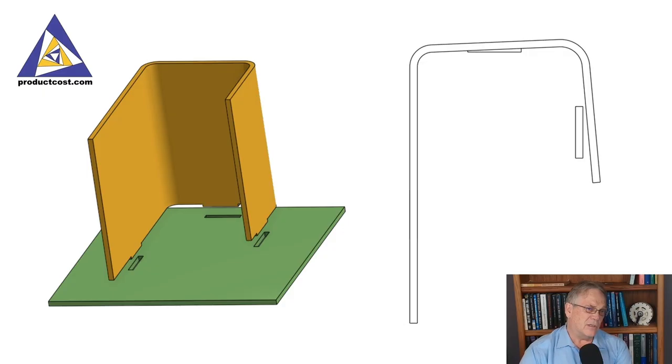Another advantage is that when you have a part that's not accurately bent, now this is somewhat exaggerated, you can actually now bend the orange part into place if it's flexible enough, and then align the tab and slot to get an accurate corner, and then do the same for the second leg of this particular sheet metal component, and thus get a fairly accurate part without having to go back and rebend it or do anything special to the part. So it has multiple advantages.